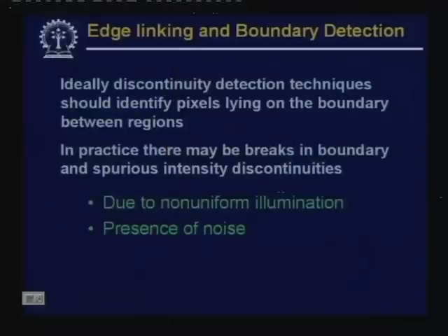If the image is noisy, then after the edge detection operation, either the boundary points will not be continuous or there may be some spurious edge points which are not actually the boundary points of any of the regions. To tackle this problem, we have to go for linking of the edge points, so that after linking we get a meaningful description of the boundary of a particular segment.